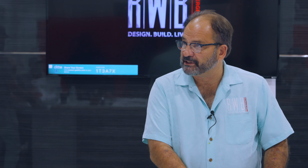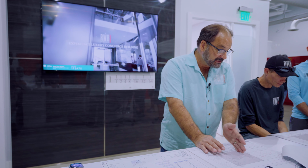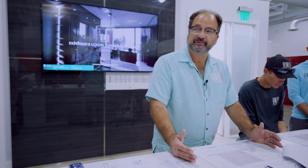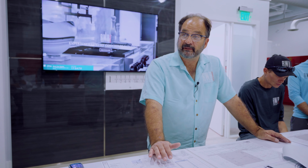The stove does line up center. You don't wind up with 3/4 of an inch to a window on one side and 1/4 on the other. So in this particular job, what we had to do is, if you look all the way on the left on that drawing, you'll see a 6-inch wall. Okay? We had to make modifications during the layout so that this stove was centered on these windows and centered on this room. Okay? All this you try to lay out before you frame. And you have to look at what the impact of whatever changes you make are.